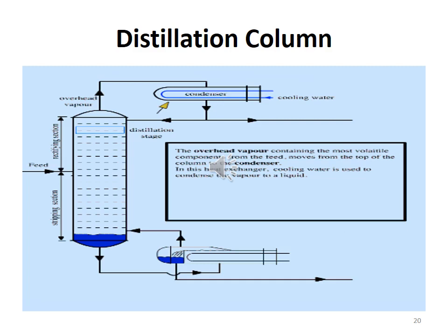So in the distillation column, the different components with the higher volatility and the lower boiling point will go up into the top section, the rectifying section. After the rectifying section, these vapors are introduced into the condenser, where the gaseous phase is transformed into the liquid state.